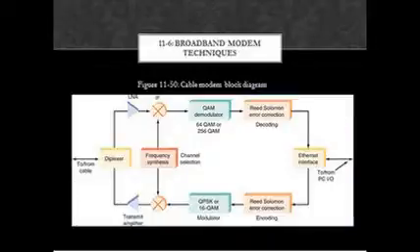Figure 11-50 shows a typical cable modem. It is basically a VHF or UHF receiver connected to the cable for downloads and a modulator or transmitter for uploads. The signal from the cable passes through a duplexer, which is a filter circuit that permits simultaneous transmit and receive operations. The signal is amplified and mixed with a local oscillator signal from the frequency synthesizer to produce an IF signal. The frequency synthesizer selects the cable channel.